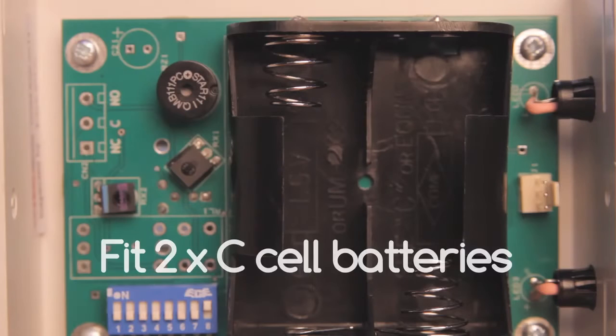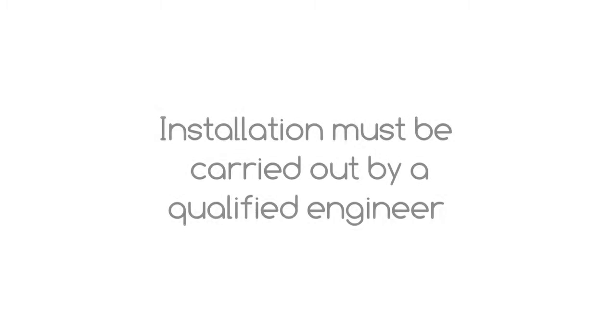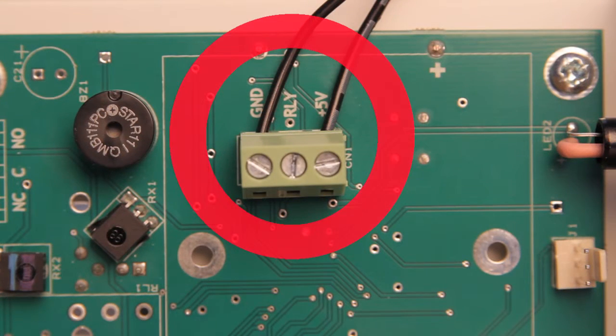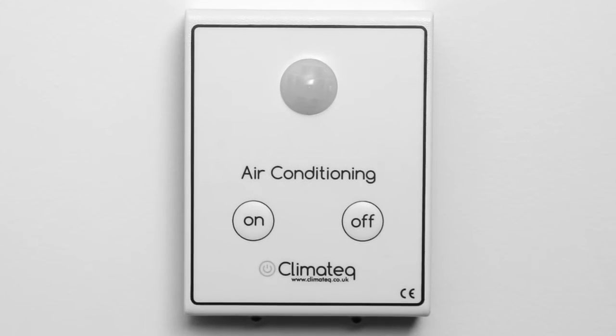For battery operation, fit 2 C-cell batteries. For mains operation, installation must be carried out by a qualified engineer. Connect the supplied mains adapter cable to ground and 5 volts on CN1 inside the attendant. Safely connect the other end to the main supply. There will be 10 beeps confirming that the power supply has been correctly installed.